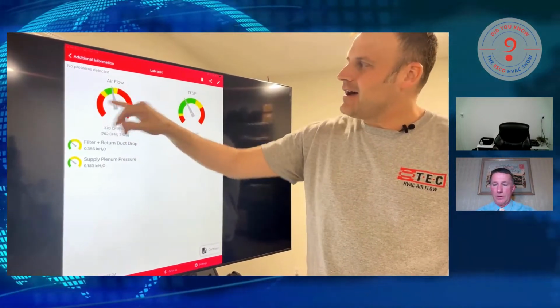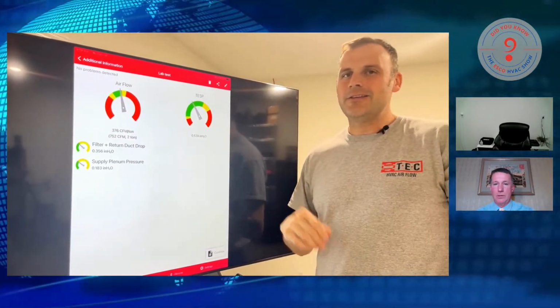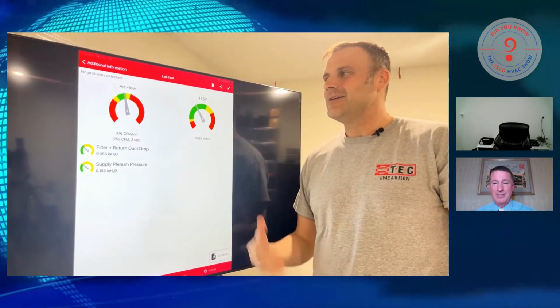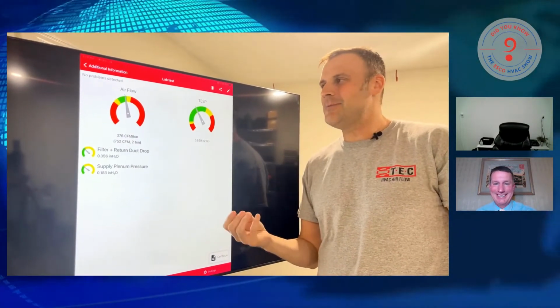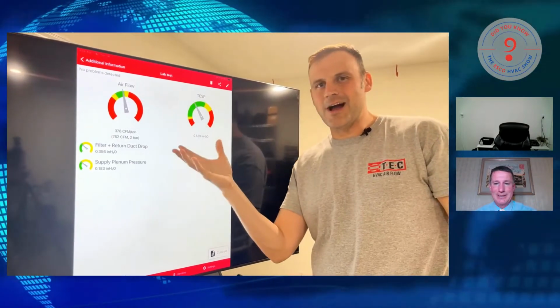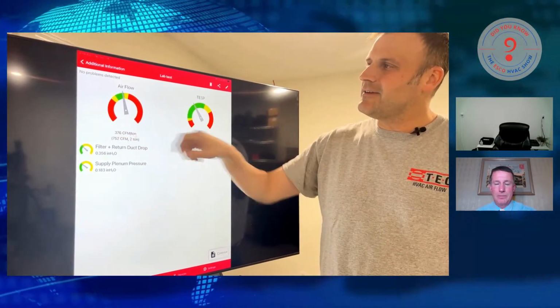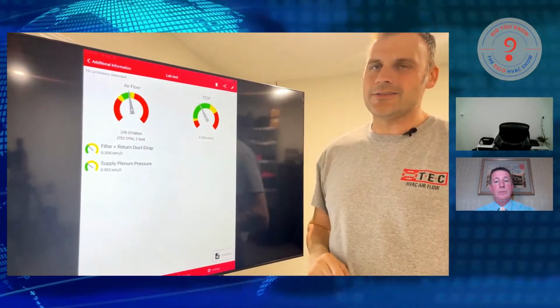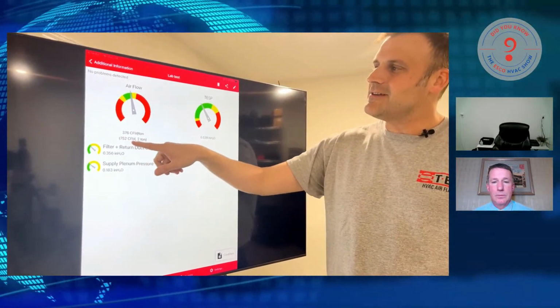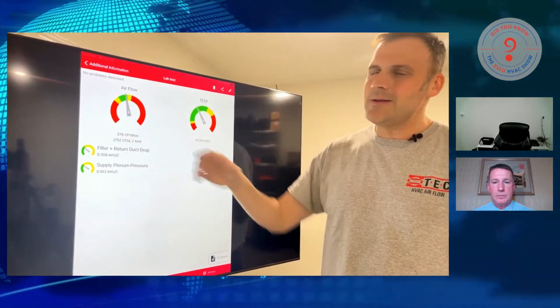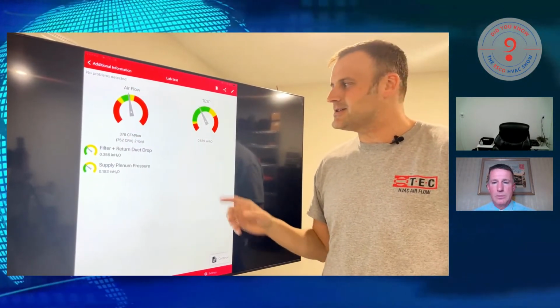And this airflow dial and TESP dial, right? These are built from advice from Ed Janowiak from ACCA, me, Steve Rogers. There was a lot of people who poured our minds into these dials, right? But look what we got right here, 376 CFM per ton. So we're in the green. Awesome. 752 CFM for the 2 ton. So we're right in between 350, 400 CFM per ton.